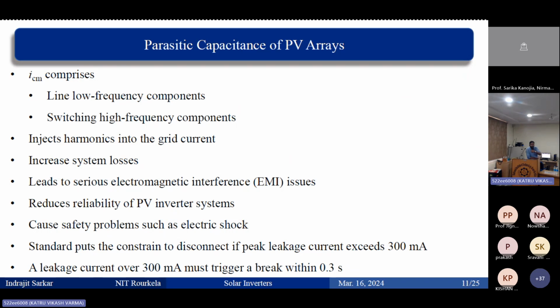When it takes peaky current, there is a drop during the peak period, and that is why that peak is a little bit down, and that gives rise to low order voltage harmonics, which will give rise to a low frequency component that is going to exist. That is why nowadays it is mandatory that every equipment you use should consume pure sine wave current, or at least harmonics less than 5%.